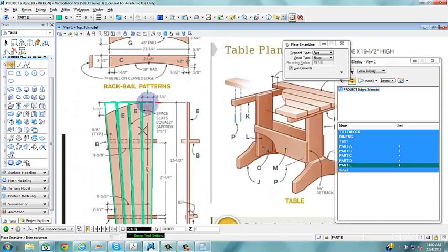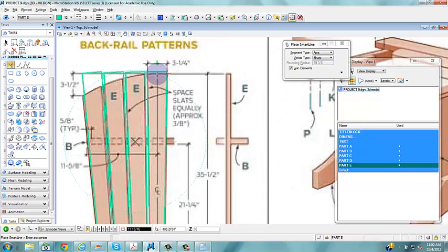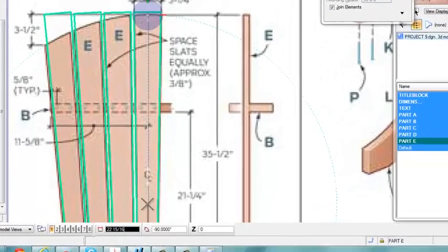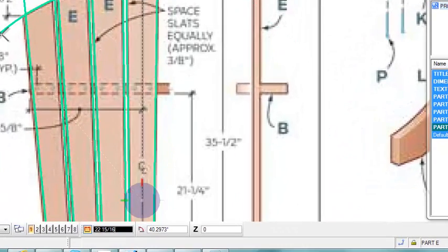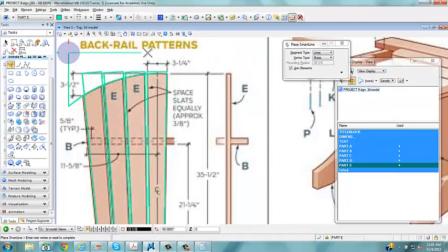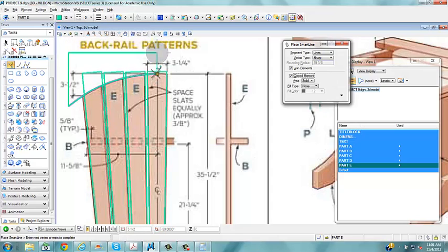Hit the tilde key. And I can see my arc. You can see this dotted line. So I'm going to bring it down until that pretty much matches. Swing this arc, hit tilde, come back straight up, I'll hit V, back here, enter, and connect it.